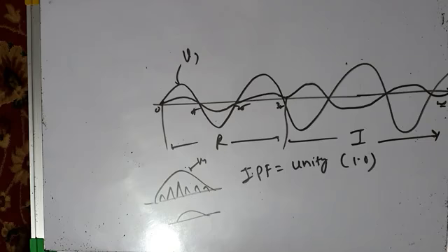If the load suddenly drops, it's turned off, and your converter is operating in open loop, then there will be continuous transfer of energy from source to load, and since load is disconnected, this energy will get dumped into the capacitor, it will keep on raising the capacitor voltage until a very high voltage appears across the load. That may damage your devices, and that may be very dangerous for the operating personnel also.